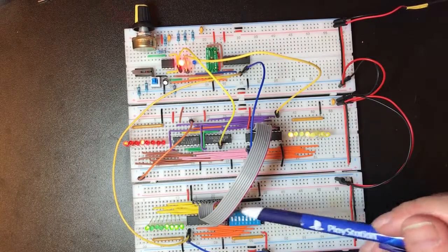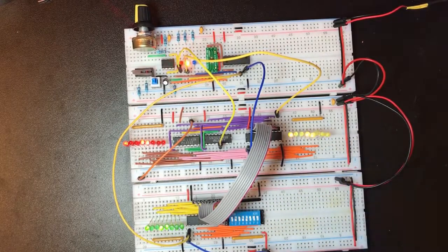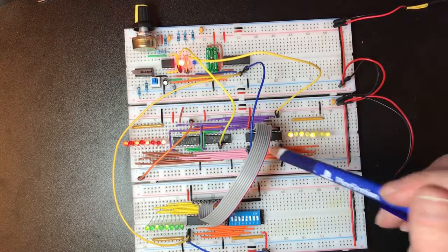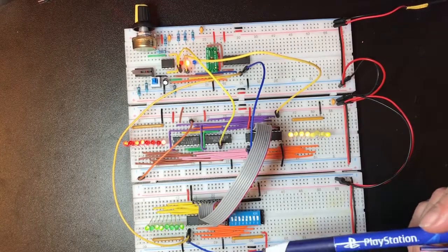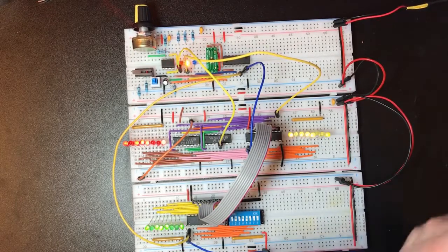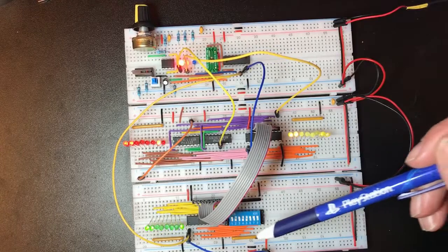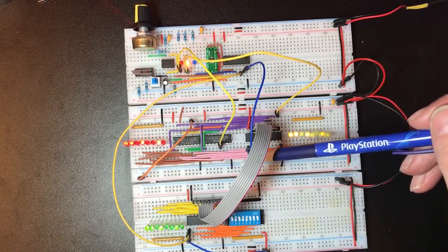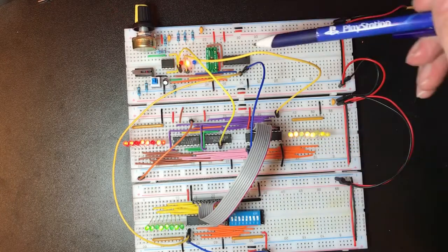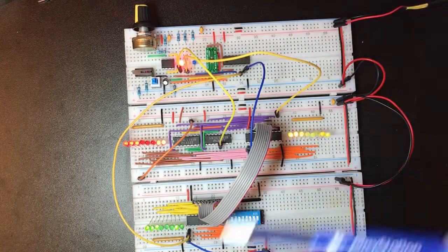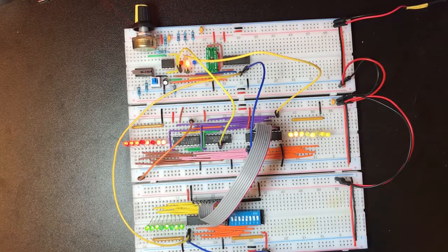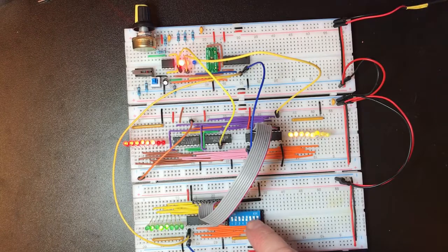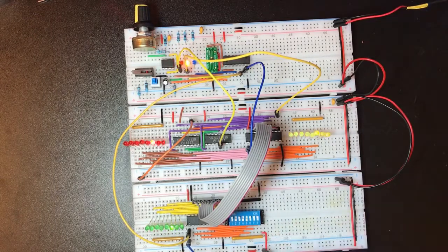We've just got two devices at the moment, but we have to ensure that only one of the devices is active on the bus at any one point in time. And we solved that problem here just by having the enable input for this chip pass through a NOT inverter from the enable input on this chip. So I can switch this and either get the output from the dip switches or the output from the counter.